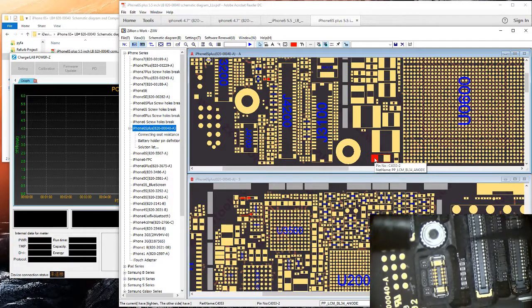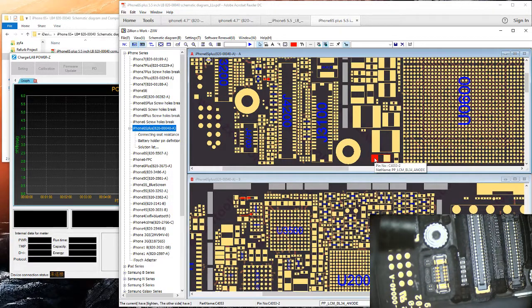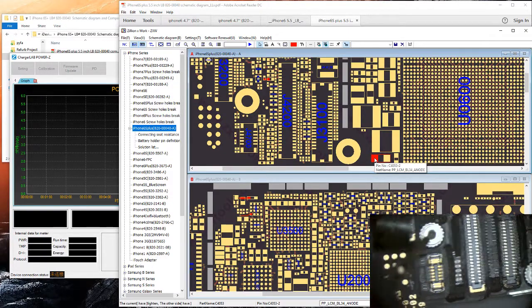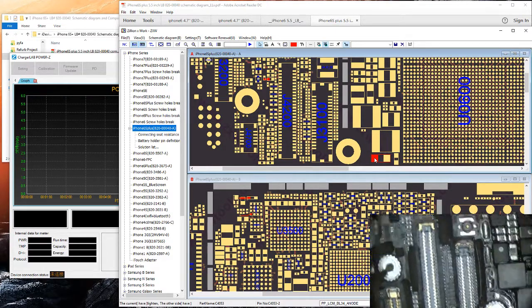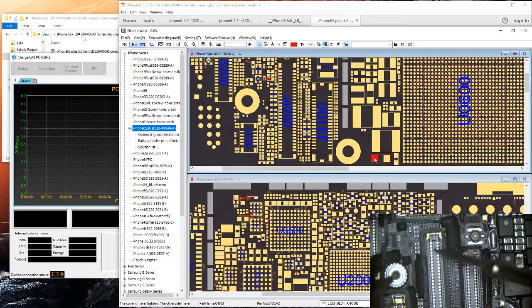So we're going to probe around. Let's get a diode reading on that anode line. It came in with half backlight. Now, whether or not my technician tested a new screen on it, I can't say. We have 505 on BL34 anode. What's 505?